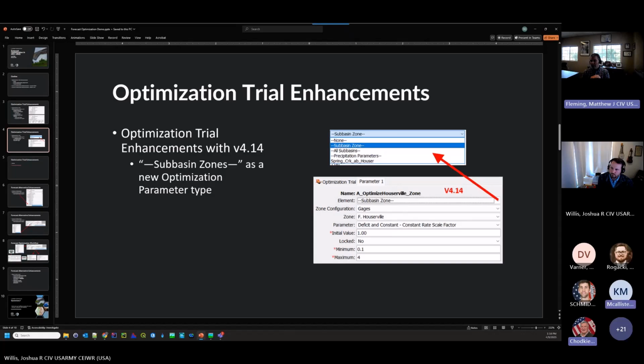What sits on top of that, though, is the initial base flow specific editor. So if you're linking the initial base flow to a gauge, then that overwrites what's in the zone editor, which overwrites what's in the basin model. So my guess is that even though optimization might attempt to find the right initial flow, the information being pulled from the gauge that's linked to it in the initial subbasin base flow is going to overwrite that. Gotcha. Yes, that makes sense.